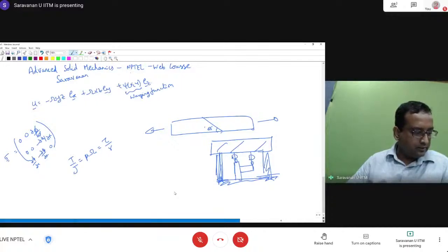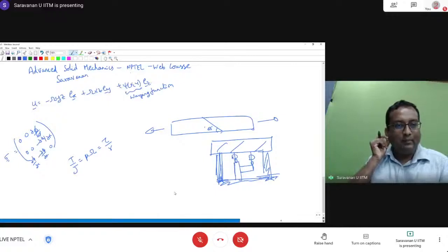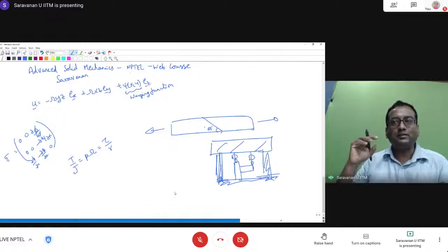What is the meaning of the three principal stresses? They represent the maximum normal stress that occurs at that point, and the principal directions give you the direction on which these maximum normal stresses occur.